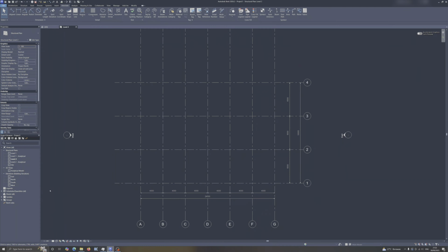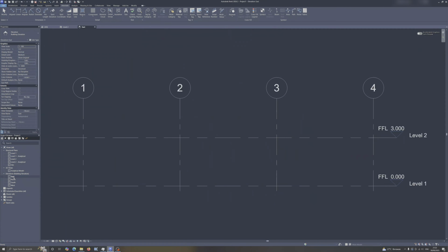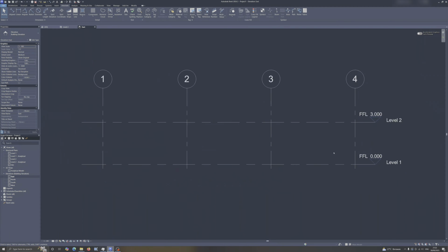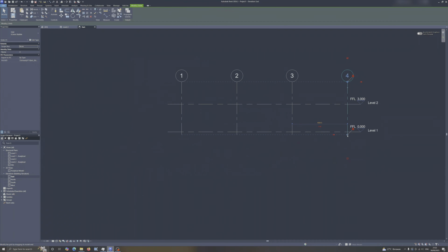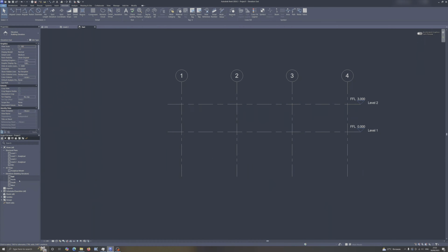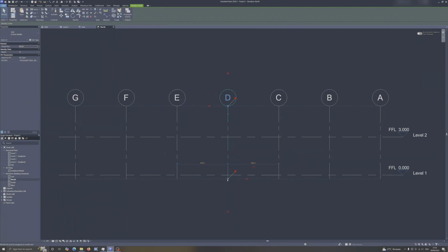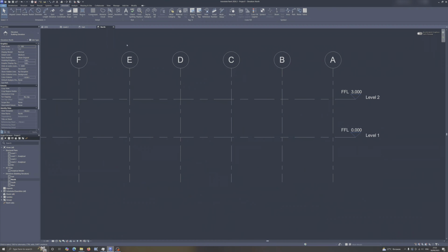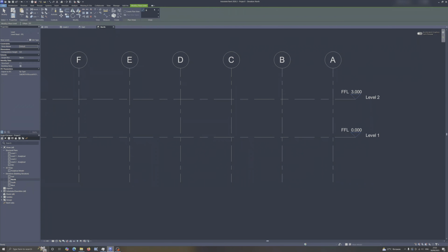So let's move on to the elevation view to check the levels over here. So let's extend these lines further down in the east and north elevations over here. And proceed to the structure tab once again to click on level over here. And choose the pick lines tool and change the offset from 0 over here to, let's say, 2 meters over here. Okay, so this is also in millimeters, sorry, so 2000.